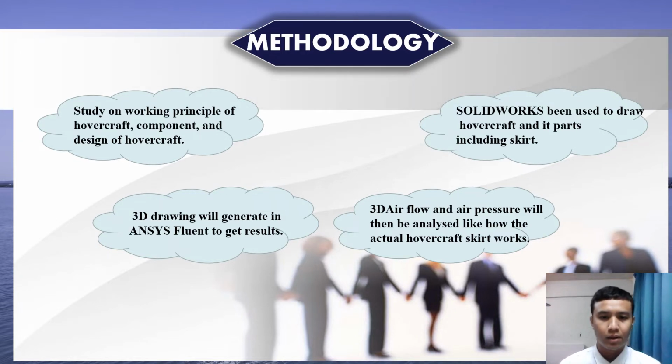Okay, for the methodology, study the working principle of hovercraft components and the design of the hovercraft. SolidWorks is used to draw the hovercraft and its parts including the skirt. The 3D drawing will be imported into ANSYS Fluent to get results. 3D airflow and pressure will then be analyzed, like how the actual hovercraft skirt works.